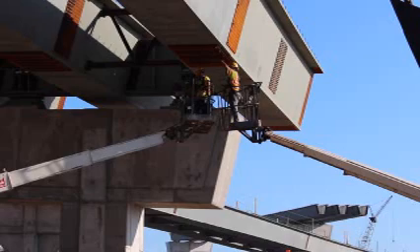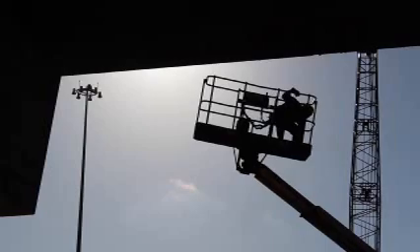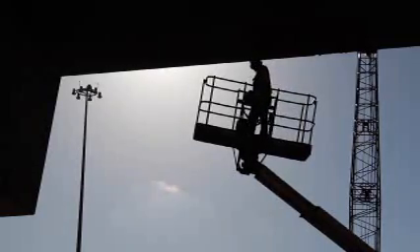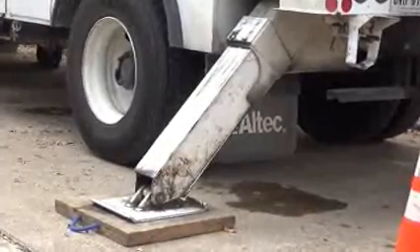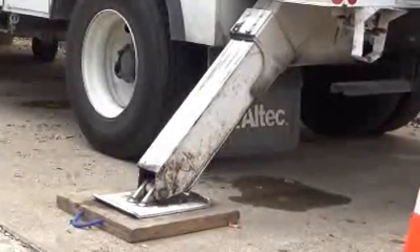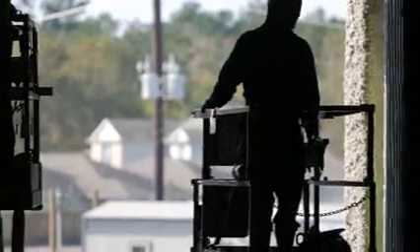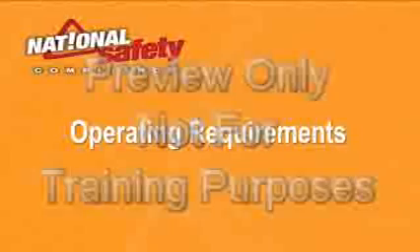All occupants of the MEWP must receive instructions from the operator and, if necessary, personal fall protection equipment must be used. Stabilizing devices, such as outriggers, should be in place as required by the manufacturer. Distribution of the platform load must meet the manufacturer's rated load guidelines, and guardrails and access gates must be closed or in appropriate positions.